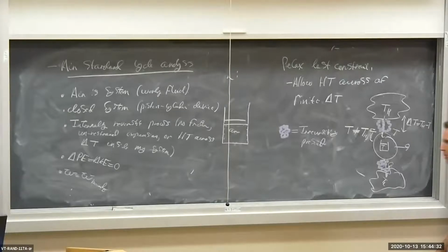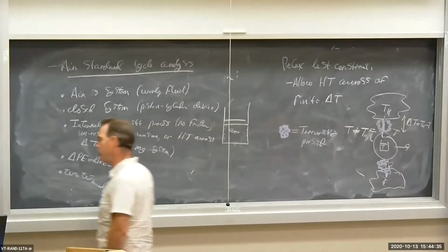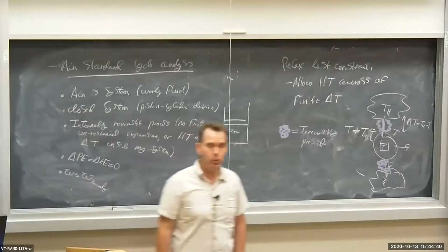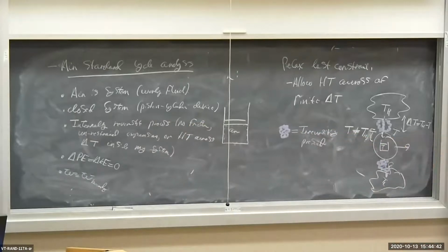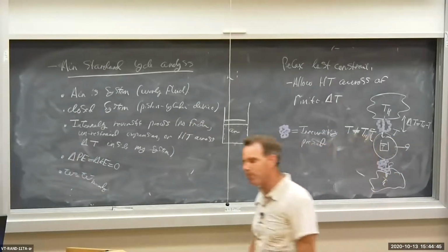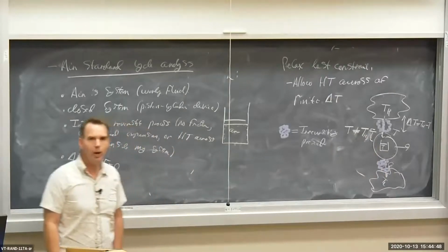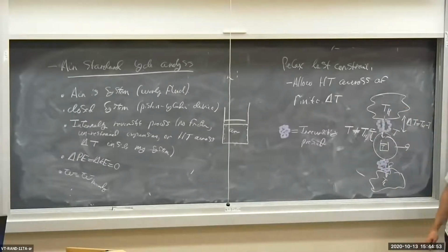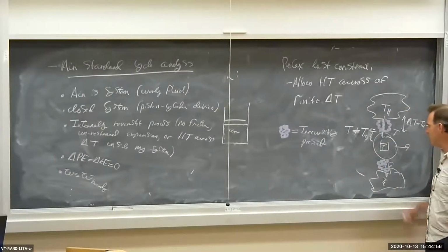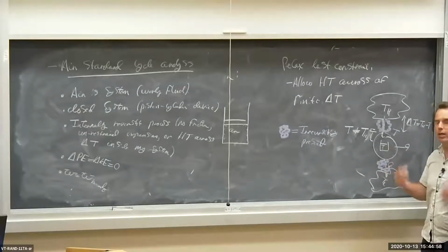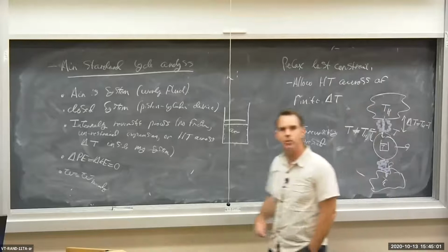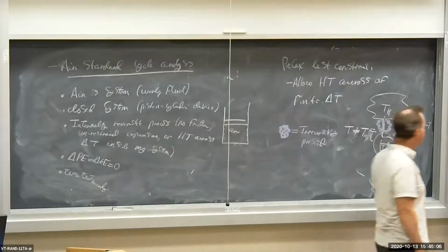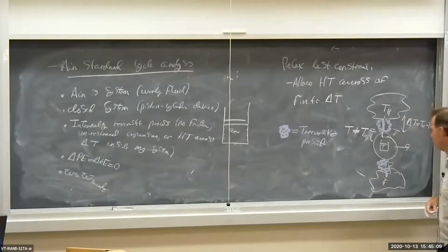Now, real devices, the internal combustion engine in your car, the Otto cycle or the diesel cycle, use the burning of air and fuel to produce heat. We're going to replace the combustion, the burning process, with a simple heat transfer process. Instead of modeling the burning of diesel or gasoline inside of the piston cylinder device, releasing heat, we're going to say that it's a simple heat transfer process from a high temperature location, or a heat rejection process to a low temperature location.